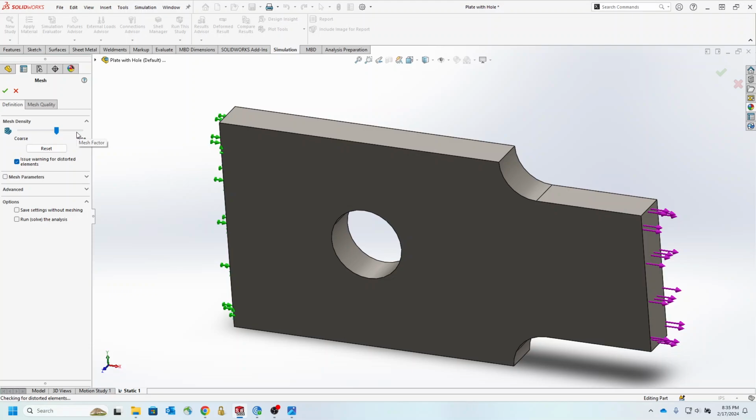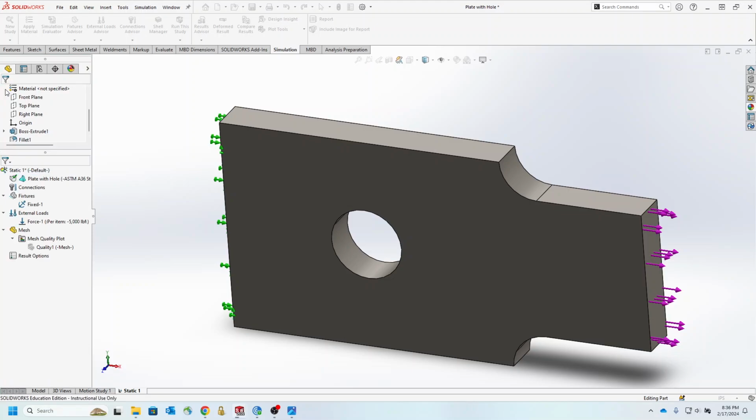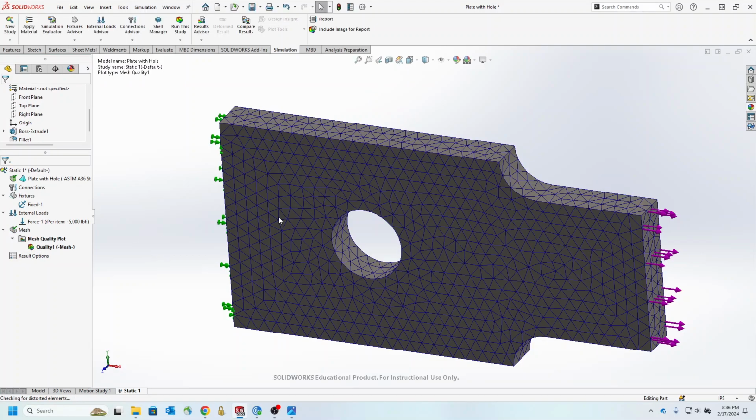For some basic studies, selecting the fine mesh does not have an evident effect on the computation time, but we have some studies that require iterations of so many calculation scenarios and frames that if you really select the finest option, the calculation time would be really extended. So be mindful of what mesh setting you choose for your application.